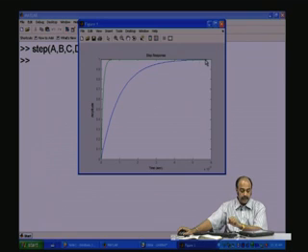And another important thing is this is a first order system, and therefore, there is no overshoot. There could be overshoots if you have LCs, the resonance effects, then you will see that this can overshoot like that and then damp out. So, these are some of the things that you will be looking for and trying to tune when you are doing your time domain analysis.